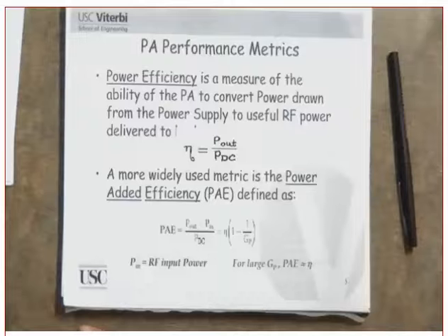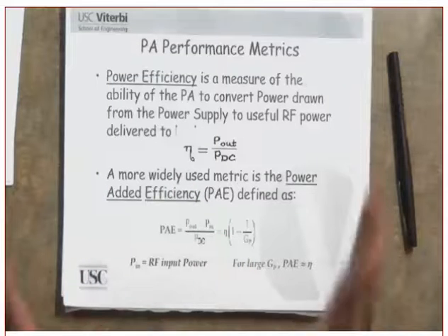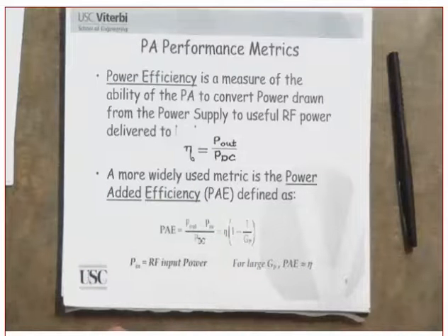So the question is, if my modulation technique is constant envelope and you are operating in a nonlinear region, the effect will be minimal. The regrowth will be minimal. Why? Because the amplitude is fixed. It's not changing. The changing of the amplitude, because of the nonlinearity, results in creating those sidebands. If the amplitude is fixed, those sidebands will be minimal. Are you following? Clear? You can afford to operate at high efficiency.